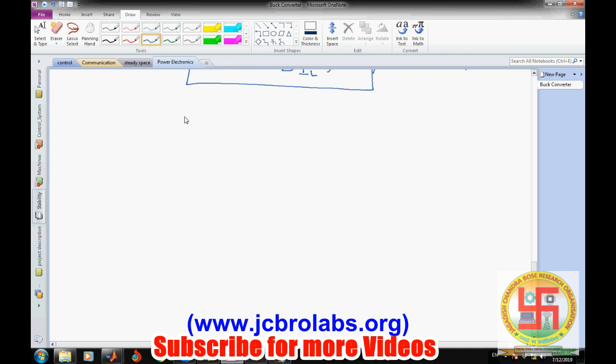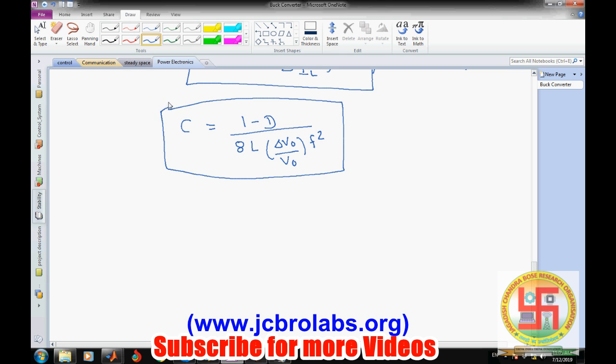The value of C, as we said, depends on the ripple voltage, how much ripple we want in the output. So this is (1 minus D) times T divided by 8 times L, delta Vout over Vout, into f squared. Because this value of C is based on the ripples which we want in the output, this formula specifies the minimum value of C.